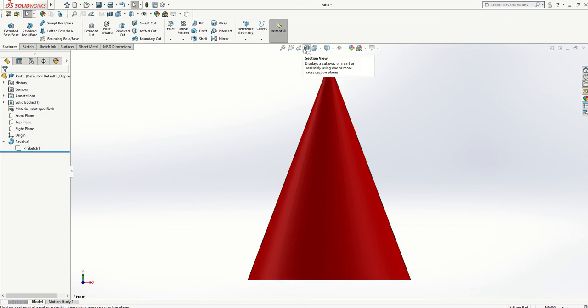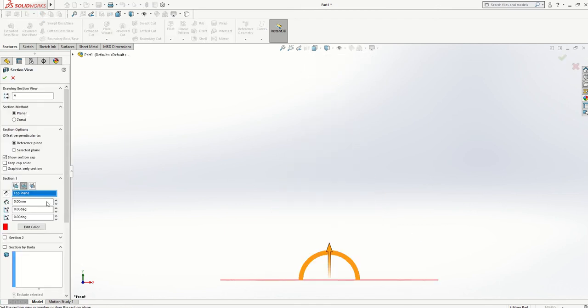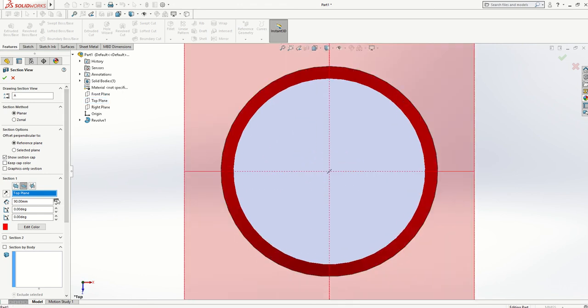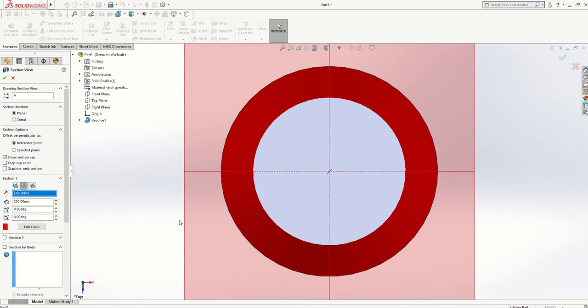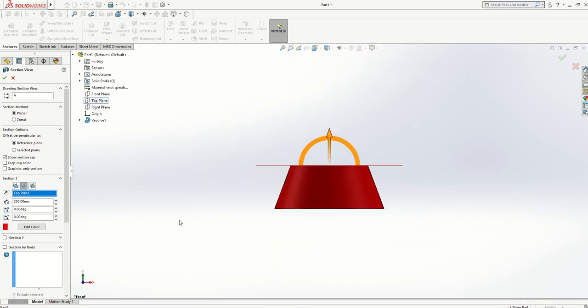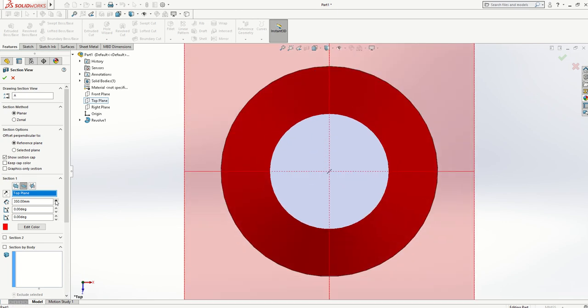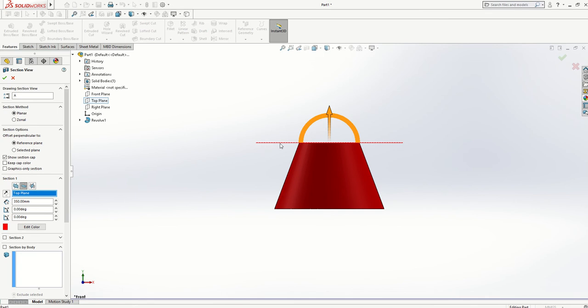Now, if I take a cutting plane, a horizontal cutting plane across the top, just like this, all I'm doing is bringing a plane horizontal to the XY line across. What we get when we do that is the resultant shape looks like a circle. The distance I bring it up will determine how big my circle is going to be. No matter where I bring it up, the resultant figure is always going to be a circle. That is when my cutting plane is parallel to my XY line, or basically a horizontal line.